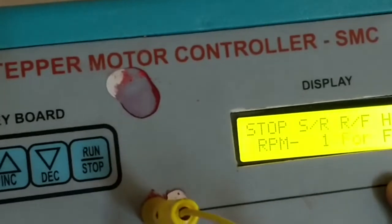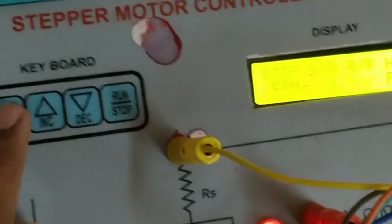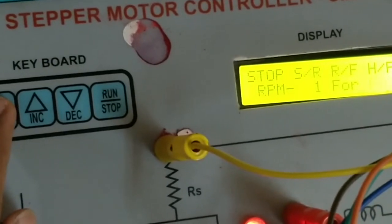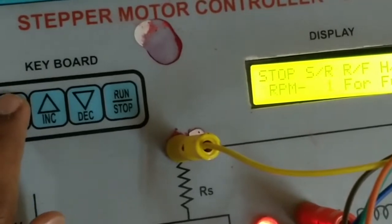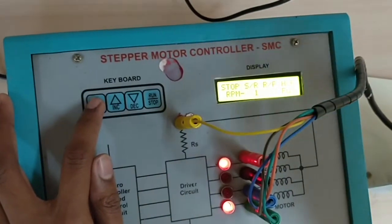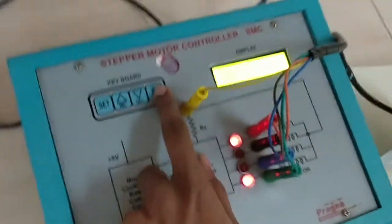And then next we'll move on to the next one, which is forward. So this means that the needle in the display will move in a forward direction, that is clockwise direction. Next you have full, which is full rotation up to 360 degrees. If you do it as half, it will go only up to 180 degrees. So for now we have set to RPM mode 1, forward and full. So this is going to be a default setting. So the only thing you're going to change here is the RPM. For our purposes, we're going to use up to 6 RPM settings, and then we're going to take the value. Okay, so I think we'll begin with the experiment.